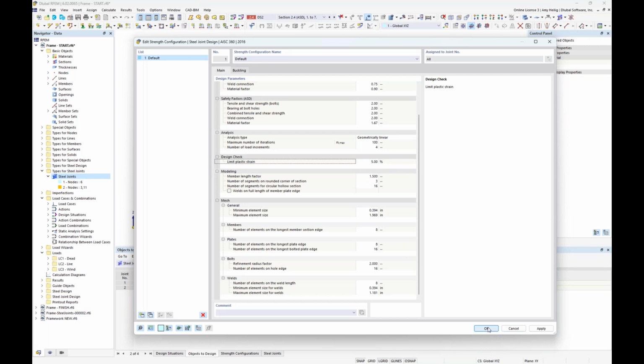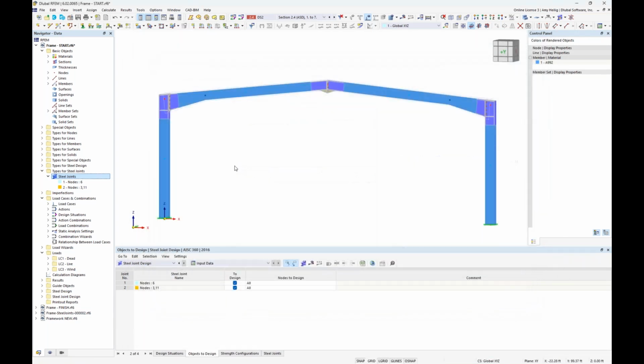So once this information is all input into our configurations, the final thing to do is to go back here to our RFEM model and jump down to the steel joint design add-on. Within this add-on in table format, we have here our two design situations, which we should remember as we covered those earlier. We have our LRFD design situation where we want to set this to the strength limit state for LRFD design. Alternatively, if I was carrying out ASD design, then it might look something similar to this, where I use my dropdown to carry out my second design situation for my unfactored load combinations according to the strength limit state for ASD design. But I'm carrying out LRFD design today, so we'll go ahead and utilize that first design situation.